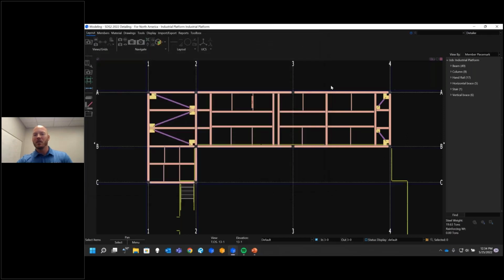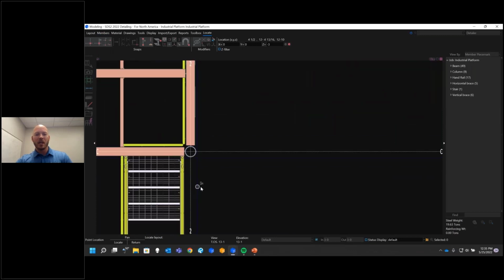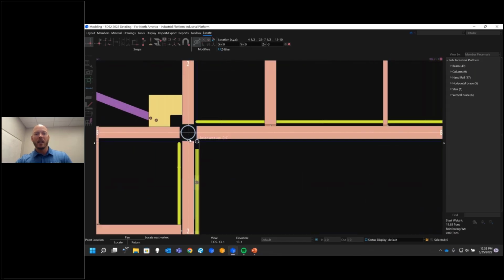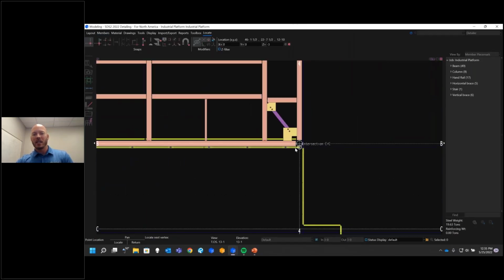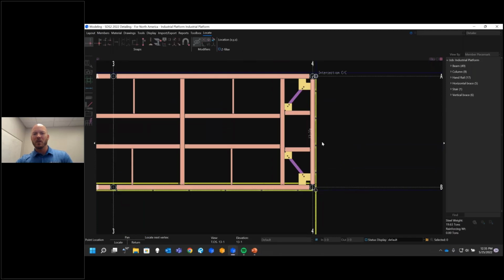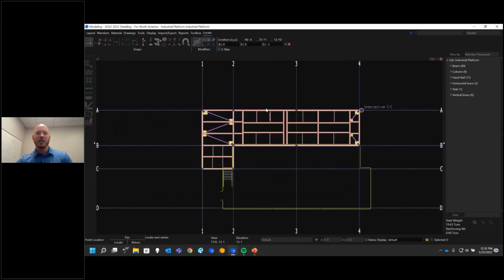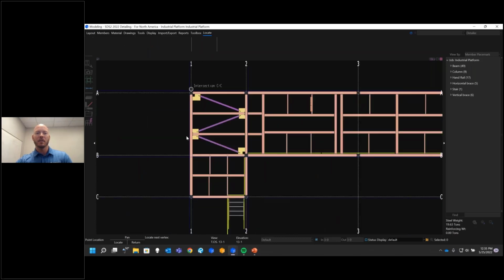Okay, so you can see some additional blue ones that popped up here that are going to help me add in my handrails. I can add individual handrails, but to start with, I'm going to use this add flat handrail command. That's going to allow me to go around here and pick points. I could have picked my points along the center line of the beams and specified an offset. I don't want to do that. I just want to do a 0 offset, since I already did that with my construction lines. Kind of a personal preference. I find that slightly easier.